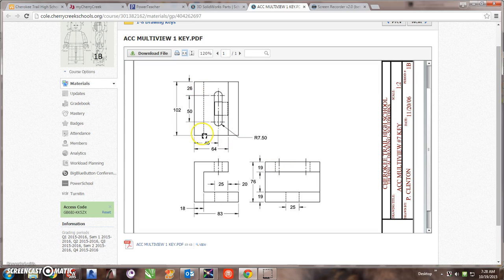Well, yes. The long, short, long are center lines. The dotted lines are called hidden lines. And they represent something that you cannot see through that surface. Okay? So like if you notice, look at the square here, part of it is a solid line, but part of it is what? A hidden line, because it has this upper part above it, you can't see through it. So you have to represent that by a hidden line.